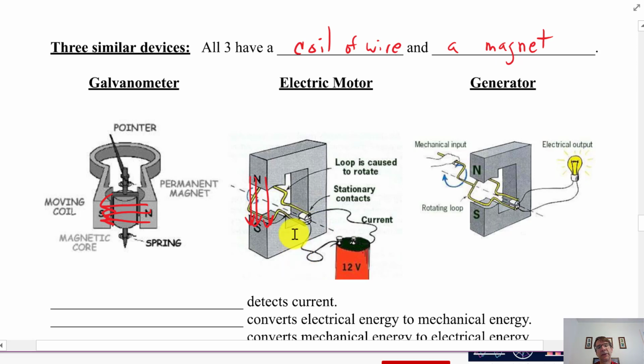It's not that fancy. So you have to have a consideration for that, and you also have to have brushes that rub so they don't twist up the wires, because the wires will get twisted up if you keep turning something. But bottom line is, the torque generated causes the loop to turn because there's two interacting magnetic fields.